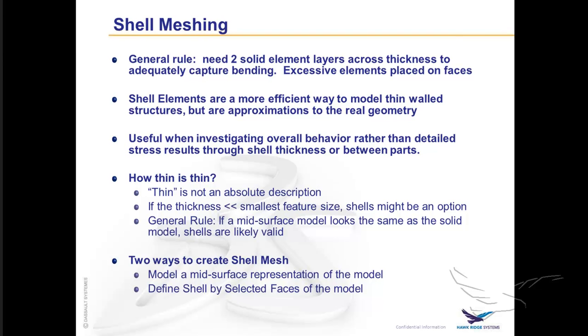You can also go by the thickness. If the thickness dimension is much smaller than the smallest feature size, shells may be a consideration. And there's two ways to essentially create a shell mesh. Model a mid-surface representation of the solid, or define the shell by selected faces.